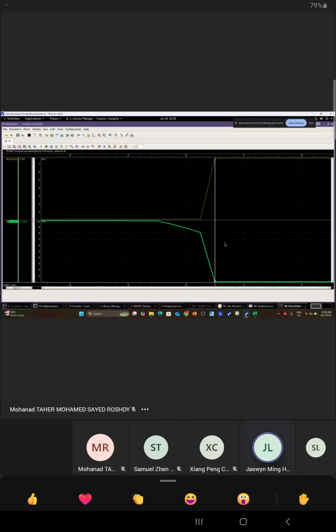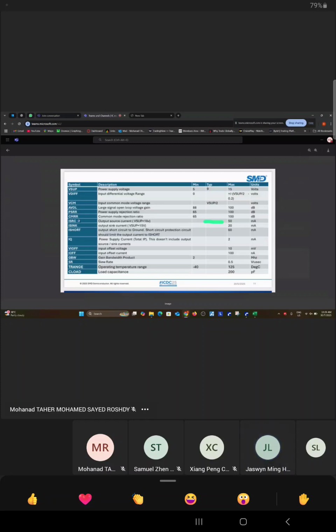I think maybe this is because the sizing used was the lowest gain or something. I'm not sure. Okay, minimum gain is how much? Yeah, that's the thing we need to worry about now, since I see that this is far lower than 100 dB. Do they have, here, open loop gain minimum 88. Okay, you try to do 20 log 7.6. How much do you get?